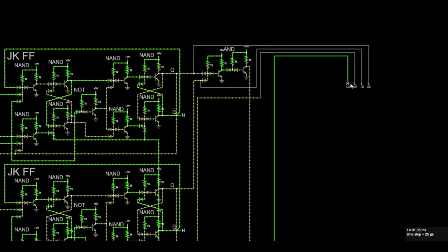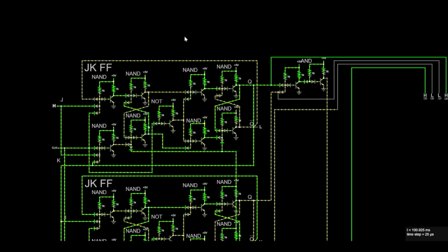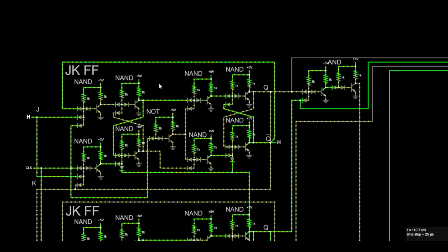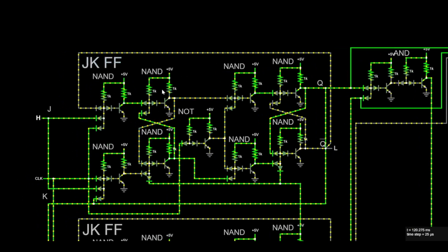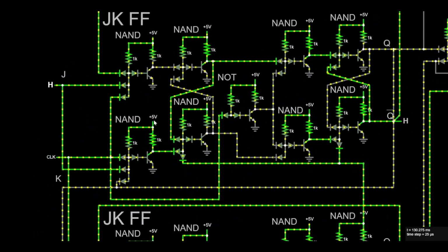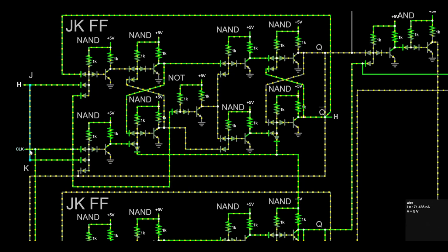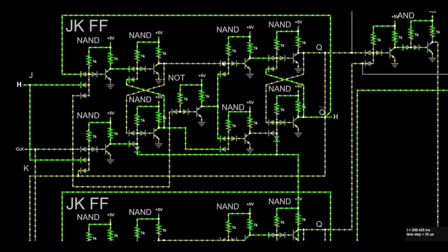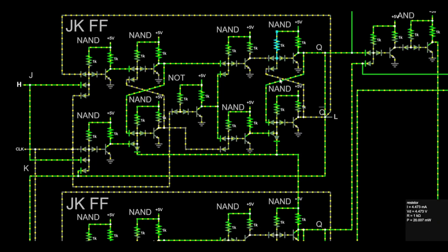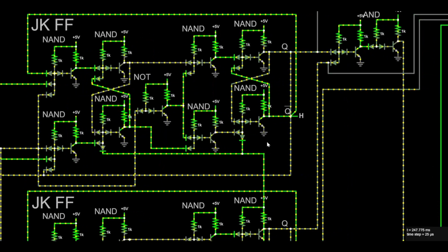And pretty cool stuff, right? It's going to work the same way the other one does. I mean, how would I mess it up? I have an example already on my screen above this. You can see it's the JK flip-flop once again, and you can see this is just toggling based off the clock. You can just track it, right? I could go through it, there's a lot on the screen, but this goes high, this flips this gate, then obviously it's flipping back and forth between these two NAND gates, and then your SR latch here, and then it's flipping this output from Q and Q not.